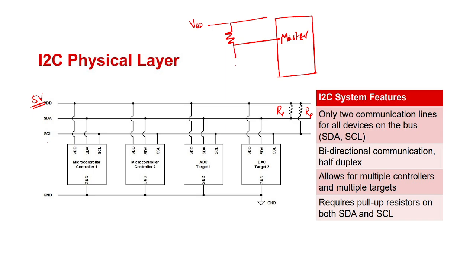This is connected with a switch, and through this switch it is connected to the slave. When the slave is not connected, it is in the open condition, so there is a path from the pull-up resistor to the master. When a slave is connected, the switch will be closed, and the master will identify that there is a path from master to slave.